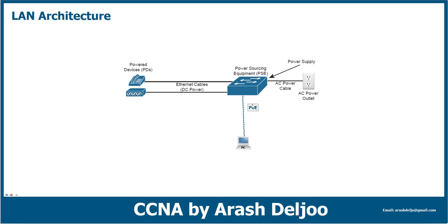You know that first we should understand that the other side needs the power. After that, we can apply the power. This is so important. I'm going to talk about this operation. Look at here. When you are connecting a device to a port of the PoE capable switch, or the PSE, first we should have a negotiation between these two devices.